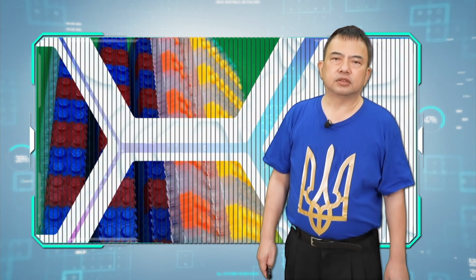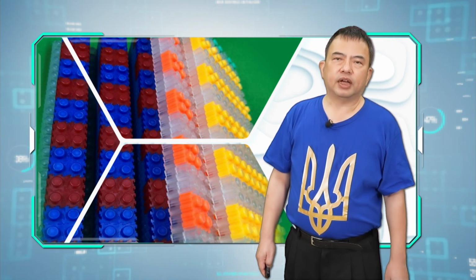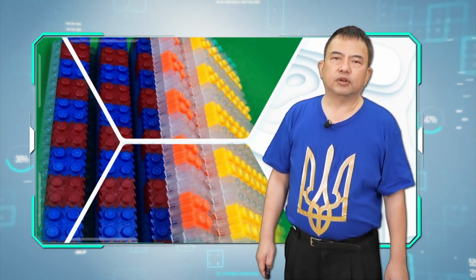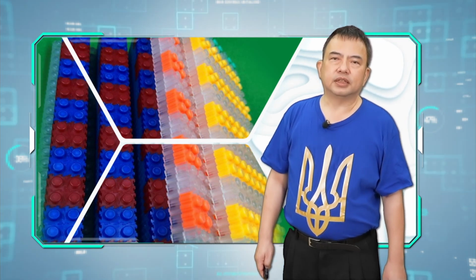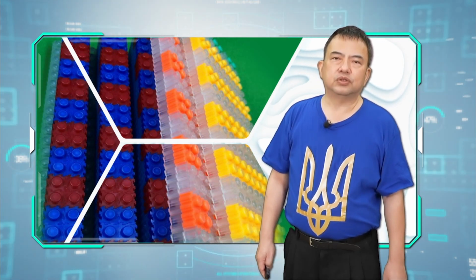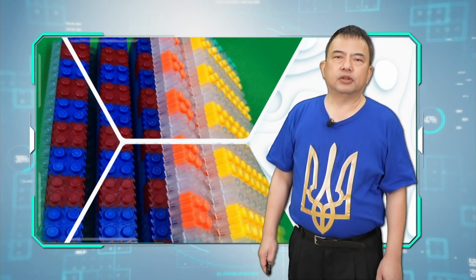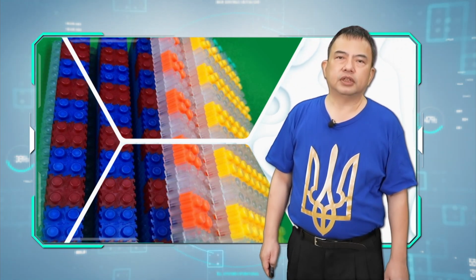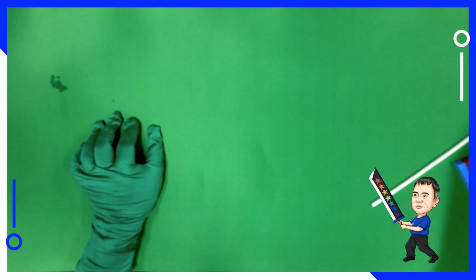And this is the 3D model, which we will show in the picture later. So you can see from the right hand is the control gate, and between the control gate and the floating gate we have an insulator in between. And then between the insulator and the channel, you can see lots of blue and red connected together with a globe in between. Between the floating gate and the channel, we have another insulator. So you can see the floating gate actually has an insulator atop it and below it.